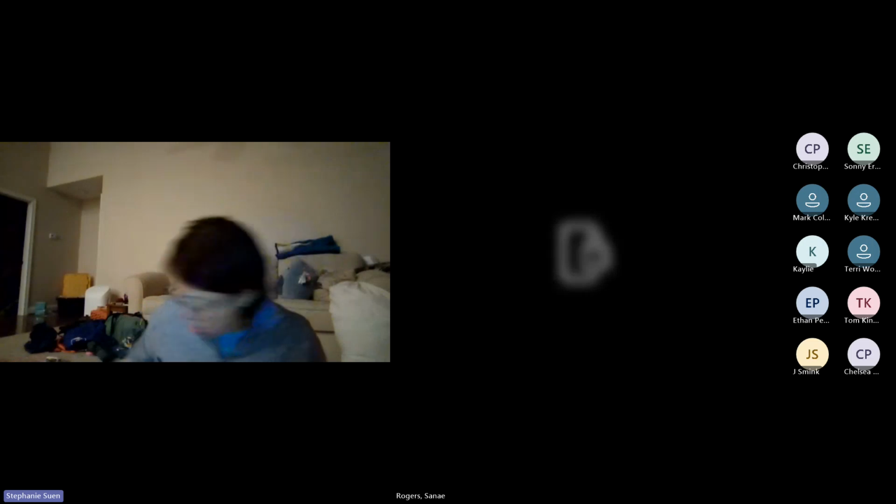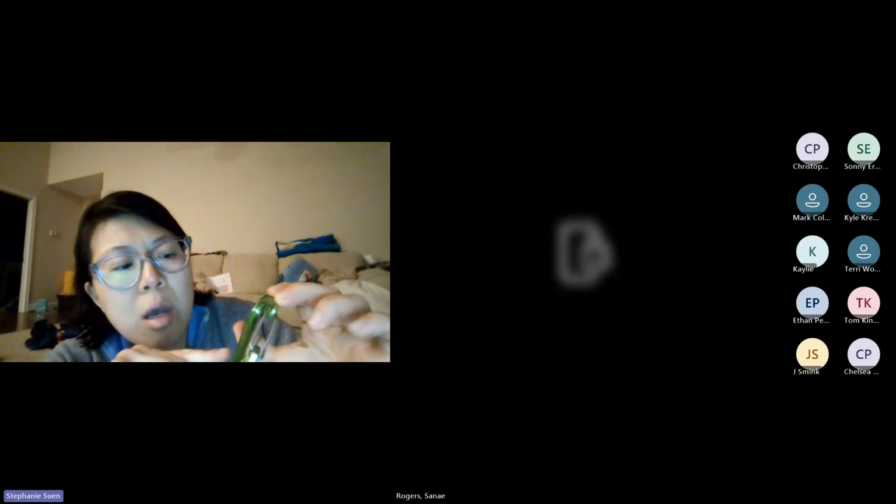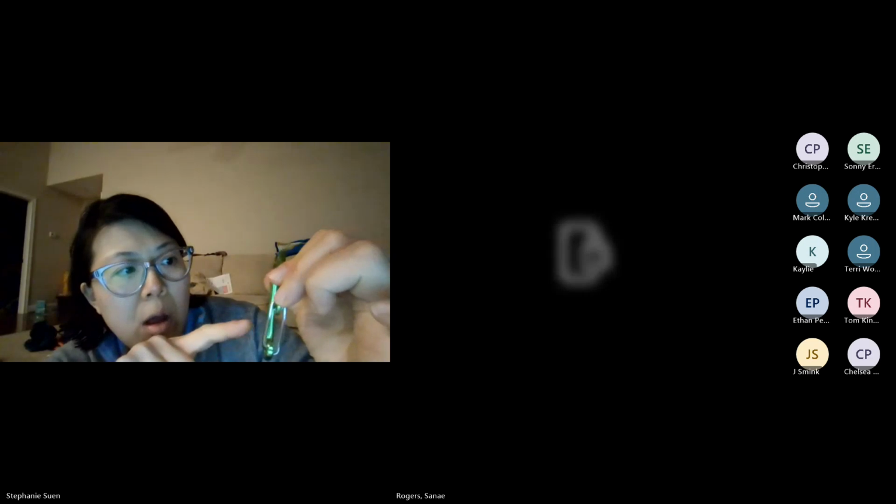So we've got non-locking and locking carabiners. If I look at the strength rating on this non-locker, I've got 21 kilonewtons along the spine, 8 kilonewtons cross-loaded, and 9 with the gate open. It doesn't tell you anything about loading on the gate, and we don't really want to be doing that anyway. The one thing to look at with carabiners is that the strongest part is down its spine. You can see this is a solid piece of metal here, whereas the opening of the carabiner is a little gritty.